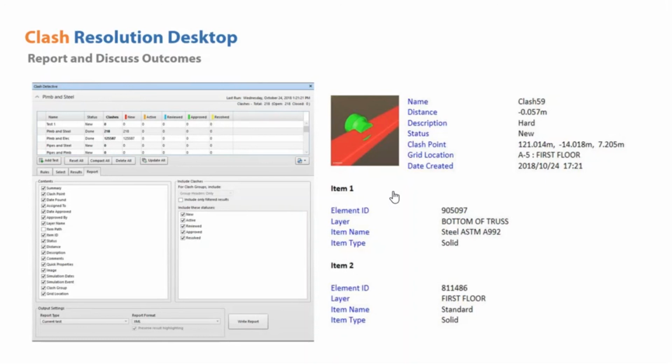And if we discuss this in a desktop environment, the goal of clash resolution is to report the output of the results of the physical interference between the building objects. Generating reports happens after the clash analysis and grouping, when the clash results have been published. The publication could be done by generating the clash reports from Navisworks, basically in HTML tabular format, or as a viewpoint, and the file can be saved in NWD format to share with the other stakeholders.